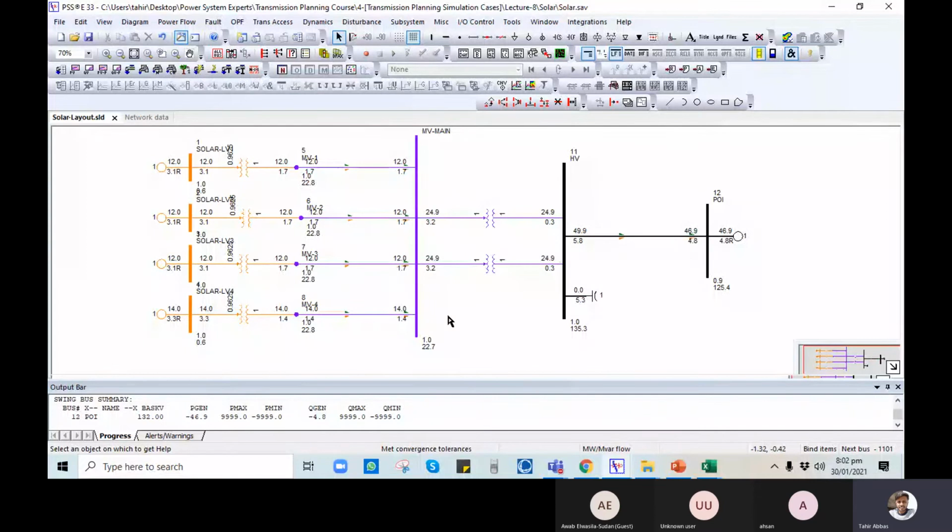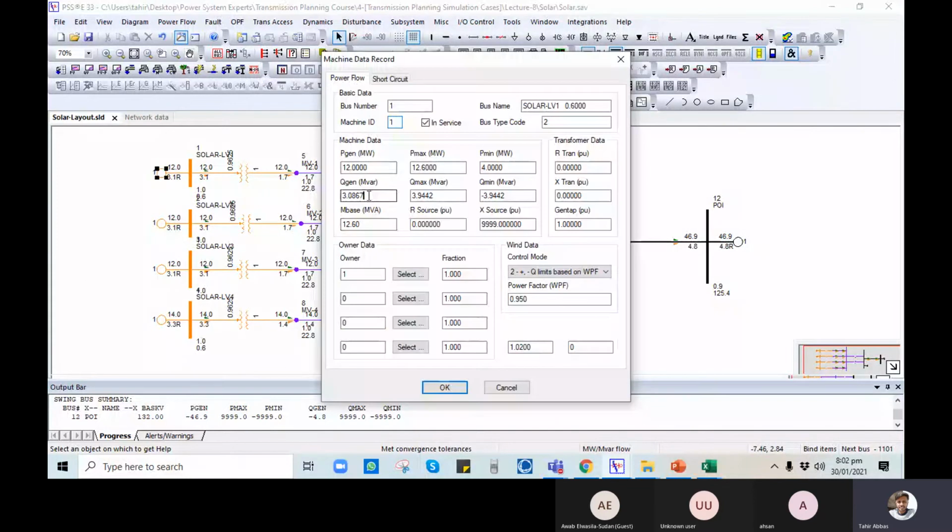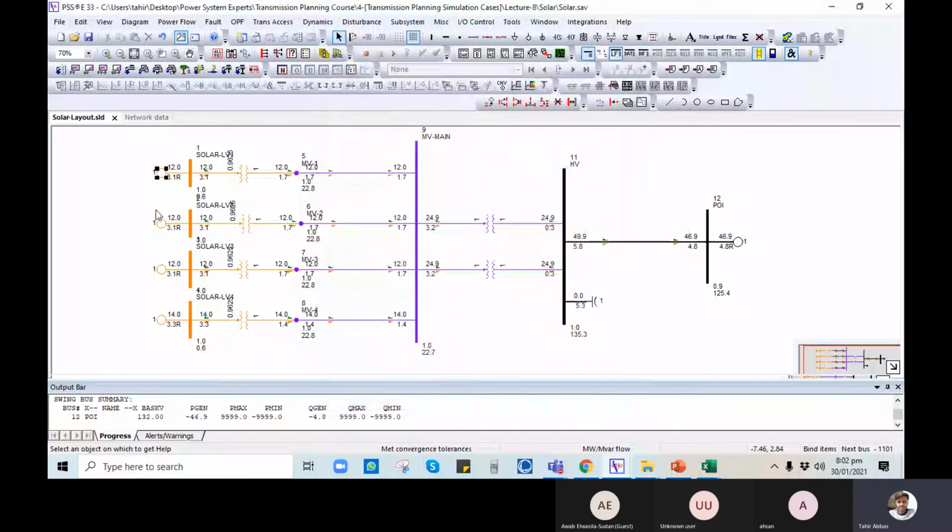Now it's more fine. The system is supplying reactive power. So in this way, now it's okay. The plant is supplying reactive power within range, that is 3.9 Q max. Look at the behavior: the MV bus is fine, and then the step up, the HV bus is also fine at 135. Look at the behavior of the grid.